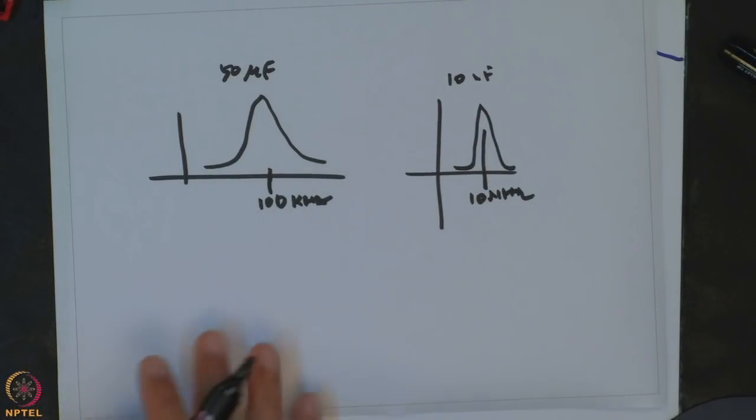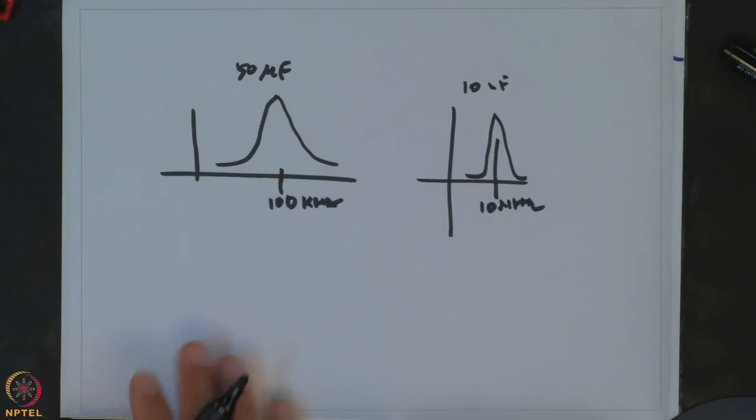Now these things are important to understand, because when you talk about capacitors, inductors, or resistors, they are not pure resistors, capacitors or inductors. They have the other elements also. For example, a resistor would also have parasitic capacitance and inductance associated with it. For example, a wire wound resistance also has a major inductive component. Therefore, we have to see what application we are working on, and only then decide whether we can use it.